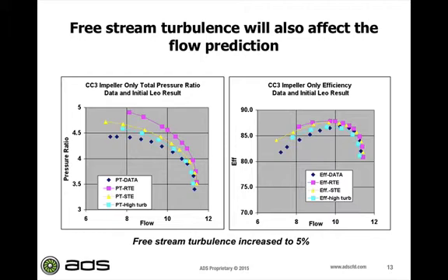However, I will not say I will use 5% turbulence for all cases, because in general, if we do it right, we will measure the turbulence level at the inlet as well as the turbulence length scale. Those two numbers need to be recorded and used in our simulation. The point I'm making here is that the constant radius cut has the most important impact, from magenta to yellow. Compared with the constant radius cut, increasing the turbulence level makes a much smaller difference than having the right geometry.